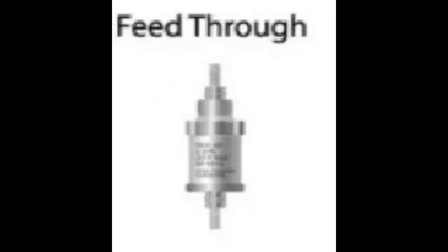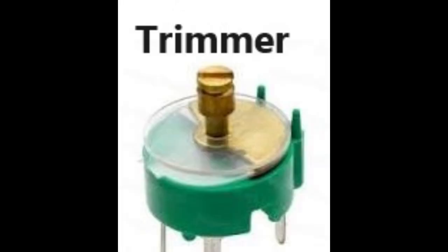A feed-through is a conductor used to carry a signal through an enclosure or printed circuit board. Like any conductor, it has a small amount of capacitance. A feed-through capacitor has a guaranteed minimum value of shunt capacitance built in it and is used for bypass purposes in ultra-high frequency applications.